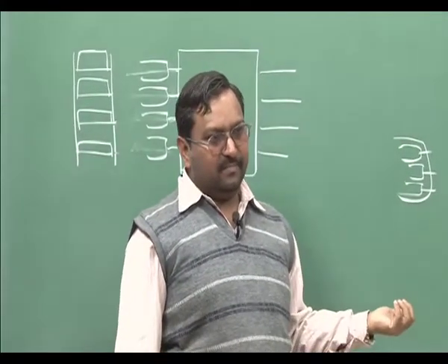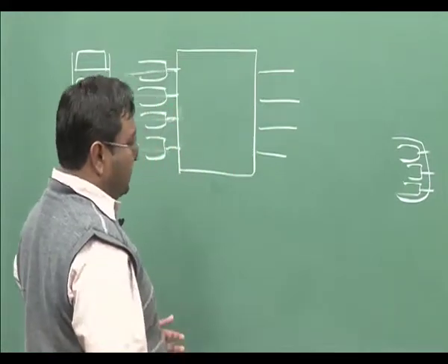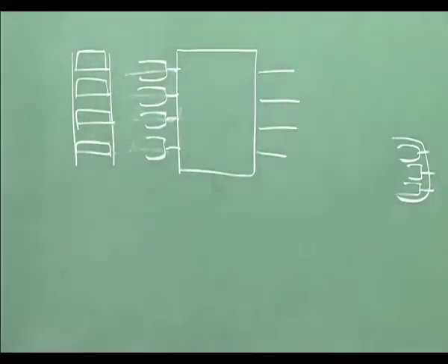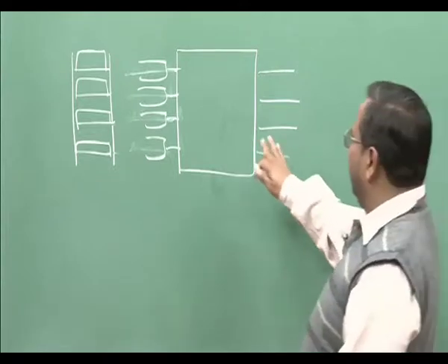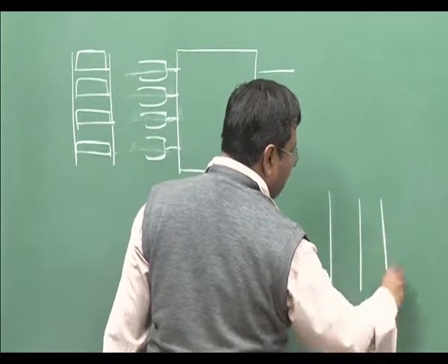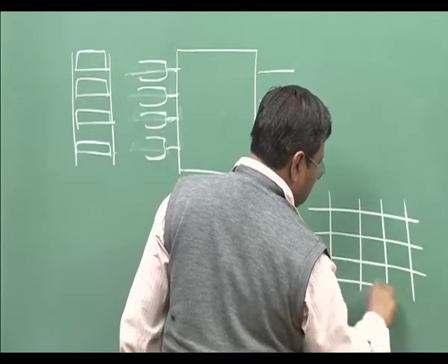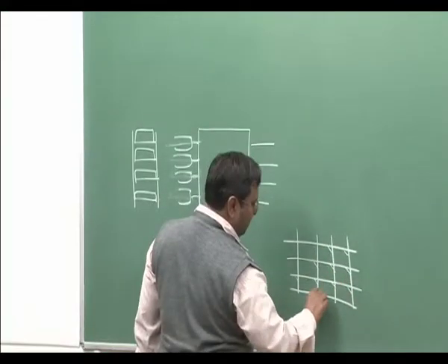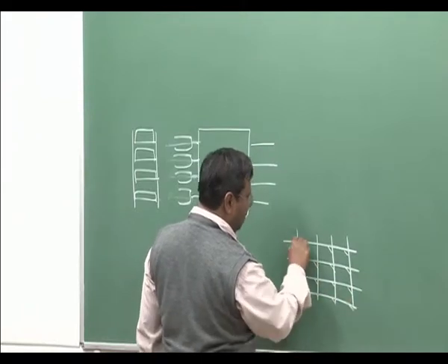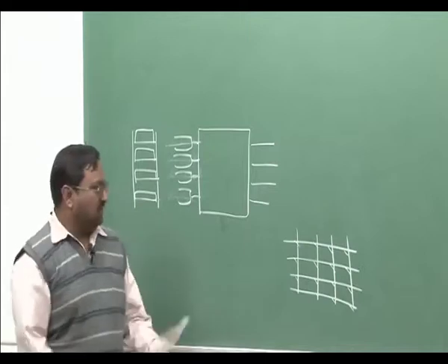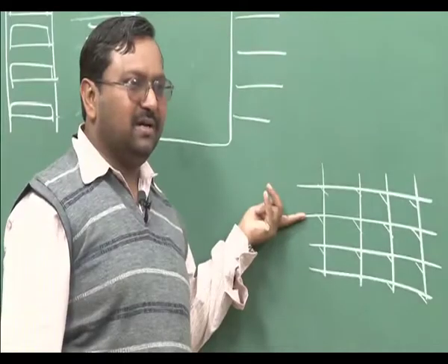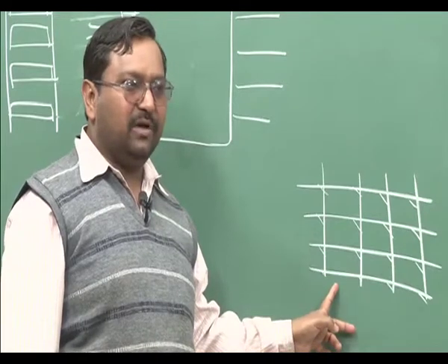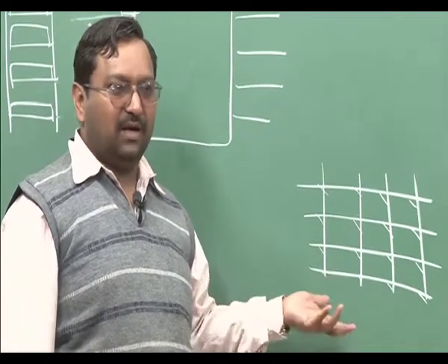But this will work very effectively. Okay. Another option was that somehow I can have a speed up factor inside the switch. Okay. The speed up factor cannot be there if it is a plain crossbar. If I use only a crossbar like this, and there are cross points which are connecting here, which are triggered for every slot depending on whatever combination is required, these lines are going to work at the same rate at which you are receiving and the bits are going out. There is no speed up factor, it is 1.